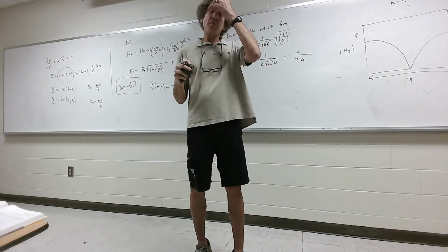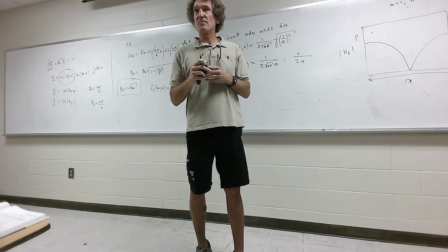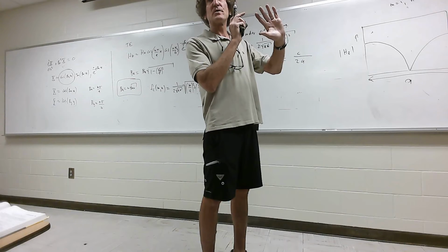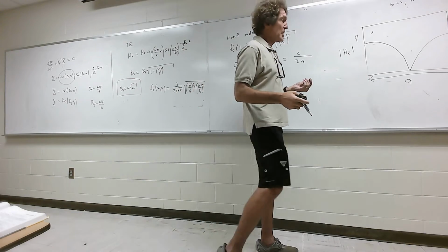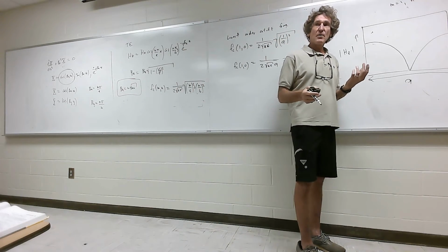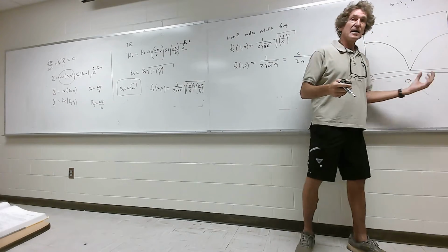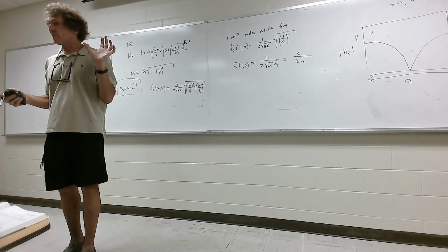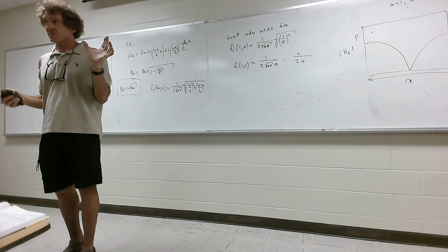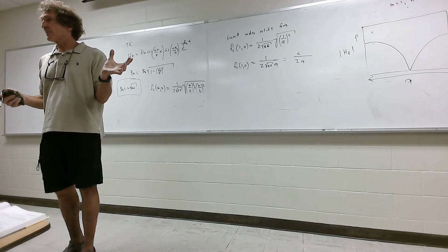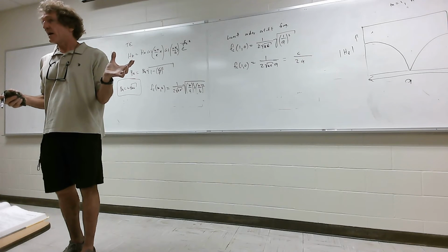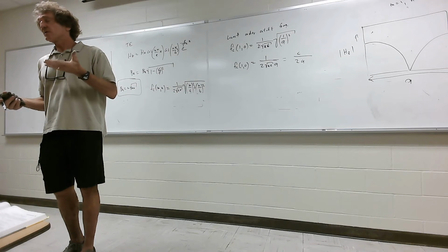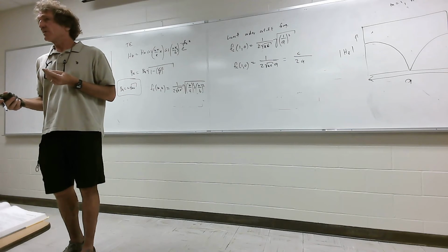I remember when I was being taught this, and I did early on, not a lot, but did plenty of research with waveguides. When you had a standard waveguide in a 1,0 mode, you know just by looking at the horizontal dimension, that told you that's half wavelength of the cutoff mode for the lowest frequency possible. So you could automatically figure out the cutoff frequency for that waveguide, and therefore the frequency of operation is a little bit greater than the cutoff frequency.